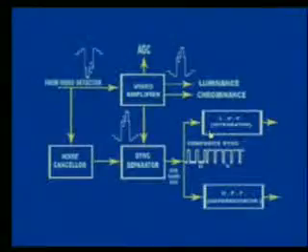Therefore, for the need of the vertical oscillator, the pulse is integrated through the low pass filter, and to satisfy the need of the horizontal oscillator, the same pulse is differentiated through the high pass filter.